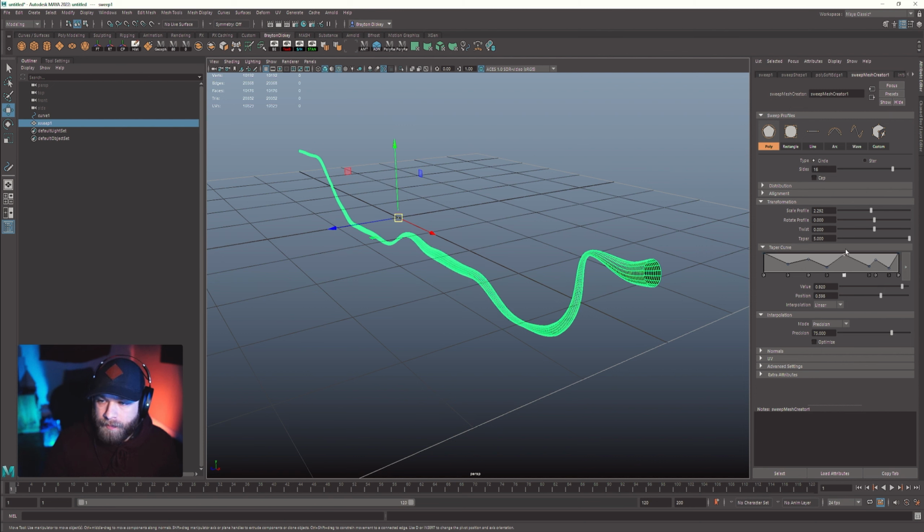So obviously the higher up here it is, the thicker, and the lower, the thinner. It's going to do this on a per point basis, as you can see. And then you can use this here to delete any points in that taper curve profile that you're doing.